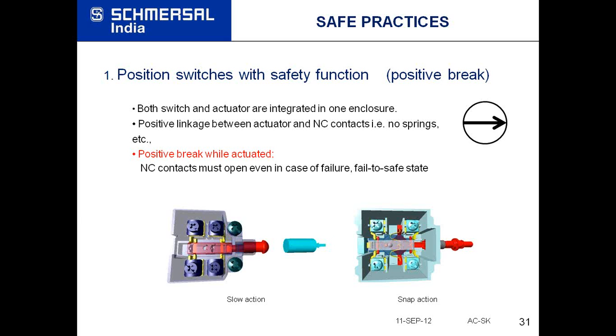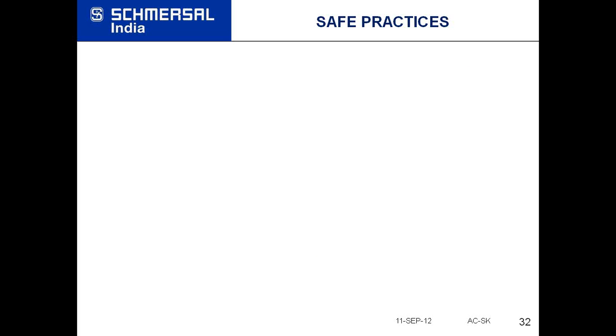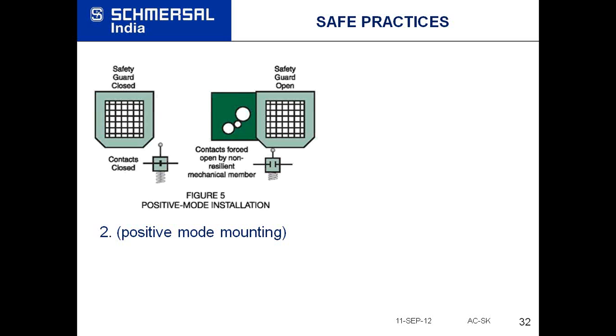Positively it will break. Okay, coming to the next safe practice. It is more related to limit switches, may not be relevant for many of you, but nevertheless, it should be mounted in a positive mode way. That means when the machine is running and the safety guard is closed, the actuator of the limit switch should not be operated.